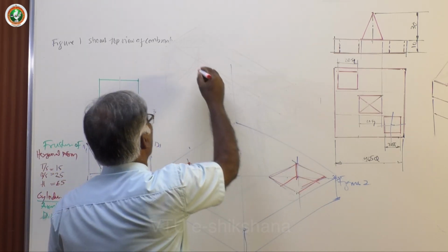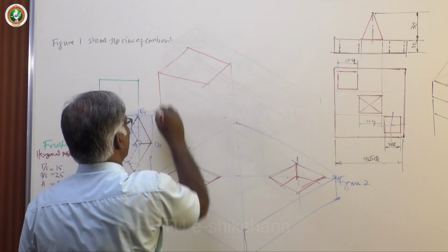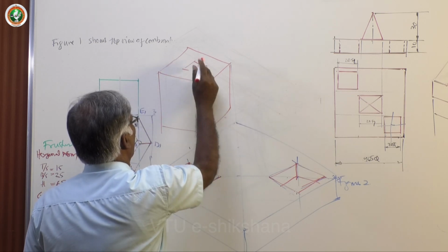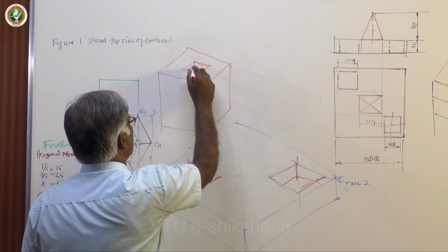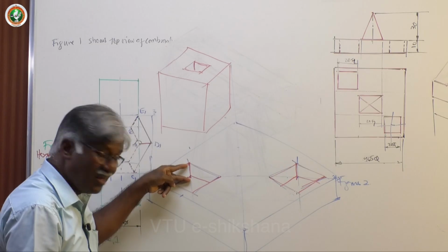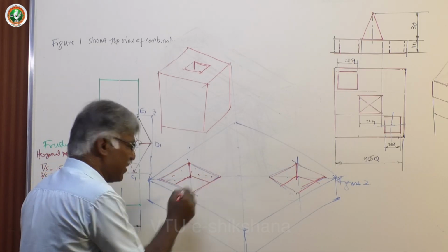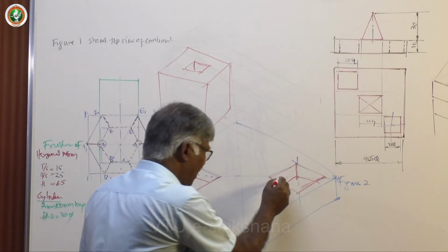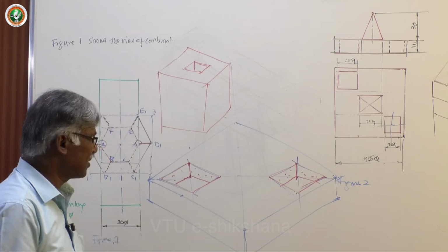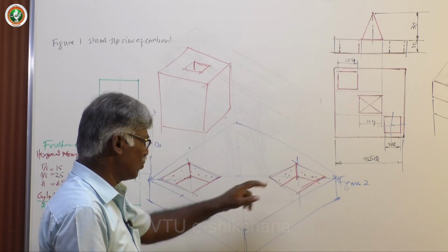Suppose that here you have a square prism, isometric, or rectangular prism, isometric. Now I have a small square hole or rectangular hole. Now I can see only this part, because the thickness is more, you cannot see completely. Here the thickness is small, so I can see the backside, rear end edge easily. So this shows a vertical surface. Again this shows a vertical surface. This vertical edge, and this towards you is not visible because it's at the back. Just for explanation I have kept the dots, to show the surfaces.